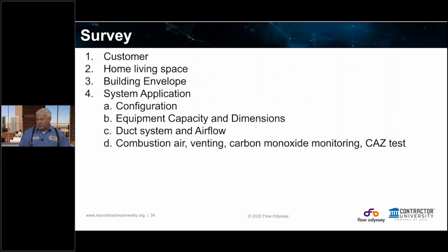Yep. For the furnace. So the guideline, based on my understanding, is if I take these gas appliances, which again, your oil appliances as well, and I take these open combustion appliances that are getting combustion air from the space itself, not like a 90+% bringing in the combustion air through the piping, right? You can take an old 40% and those stays, they're not going to really see. But there's still a lot of them out there.